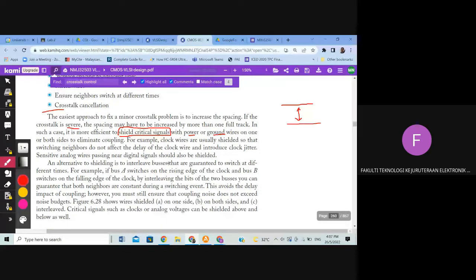Another example is the clock. We know clock. We use the clock all over our chip, throughout our chip. You recall back what you did in your lab, lab number 2. You did the layout, automatic place and route, and then you see the clock there, and how the clock reaches the clocking elements. It actually goes through a long interconnect.